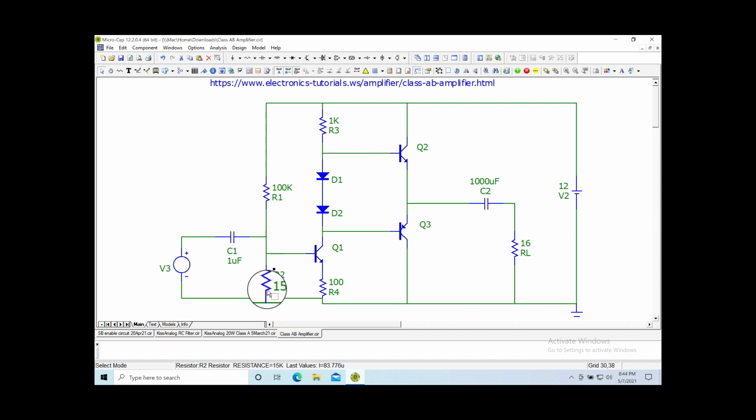That was just an extra line. You could end up with, I've had that happen before, where I accidentally leave a wire trace underneath the resistor component and it's shorted. And I finally find it later when I look at it close. We're zoomed in here pretty close. We can see things pretty well. But okay, let's go ahead and run the simulation.